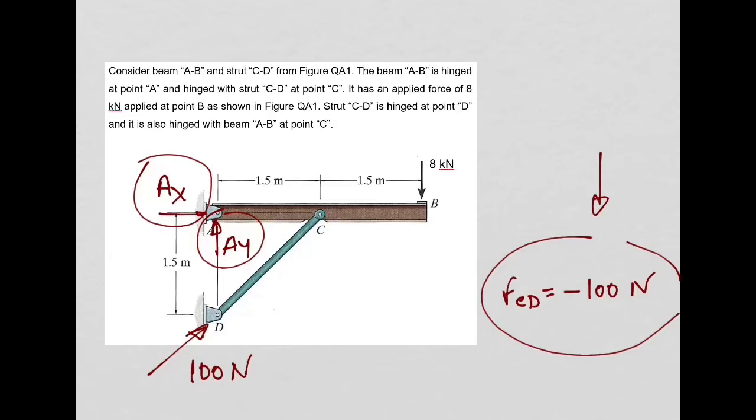Okay? Because if you arrive at this point, it means you calculated the resultant of the forces, you evaluated the moments, you wrote the equilibrium equations, right? You did everything, right? But this is what it means. When you get a negative value for a reaction, it means your initial guess for the direction of the reaction was wrong. Then you need to go back and reverse. But we are going to do now this example.